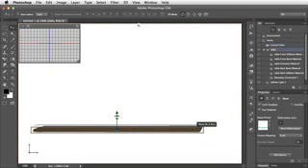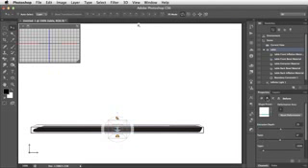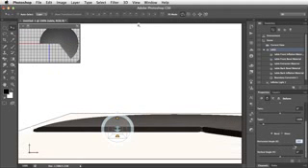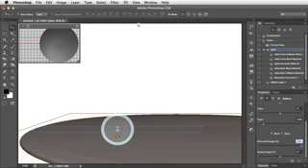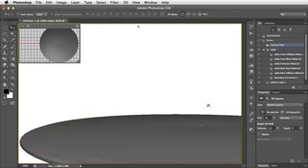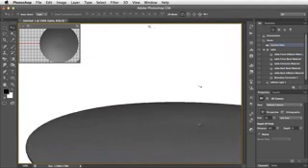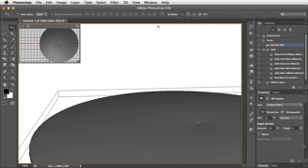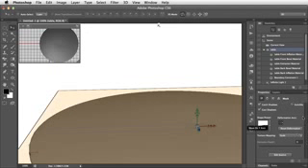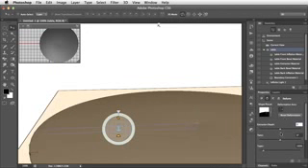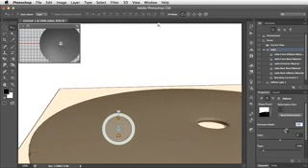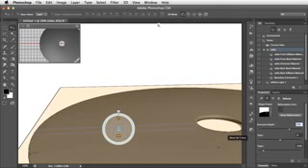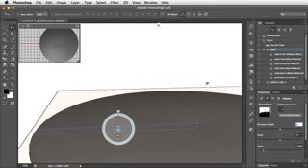Once again, we know what to do. We go to the Properties tab, we'll select it, go onto the Deform section, deform on the right hand edge, set the extrusion to 0 and the bend angle to 360 degrees. And there is our table, easily made in just a minute or so. If we wanted to make this an outdoor table with a hole in it for an umbrella, well, we could do that as well. All we'd have to do would be to increase the extrusion depth and there's our hole in the middle of our table. But let's leave that as it was.